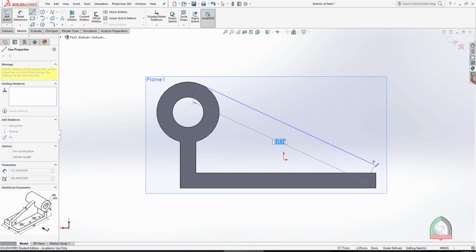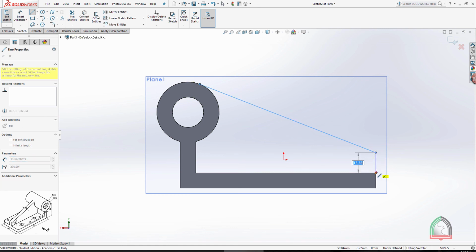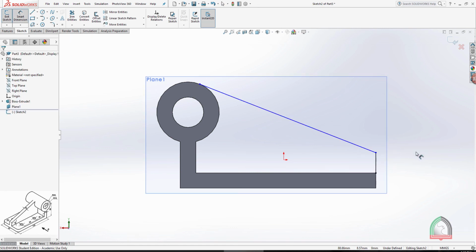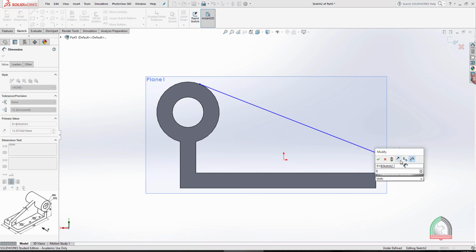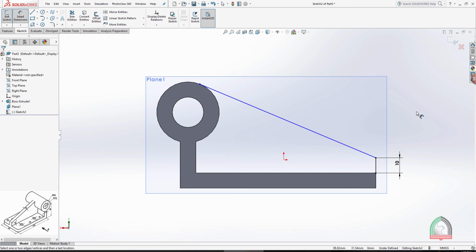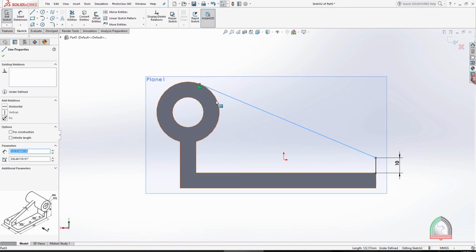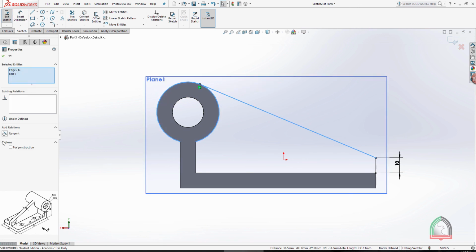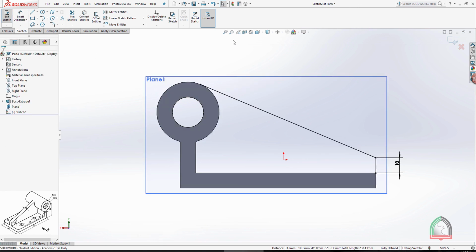Here you will get the snap. Okay, I got the snap. Now the height has been given, the height is 10 here, and also there is a relation: the line and the arc have a tangential relation. Now we can either take the fillet from here or make the fillet by using 3D. I'm going with 3D now. I'm leaving it here like this.